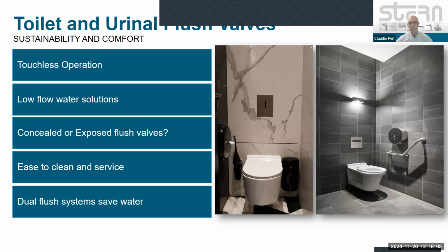In the latest specifications we see in Canada, the tendency of architects and interior designers is to specify more concealed versions than exposed, simply because they also provide a more minimalistic look in commercial applications. Of course, they are easy to clean, service, and maintain. Usually, by removing the security screws on the wall, you can have direct access to the components inside the WC or urinal in order to perform or support the installation.